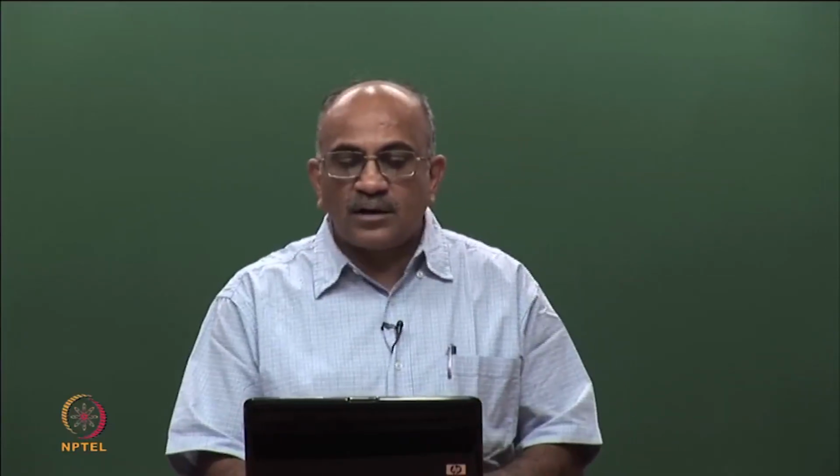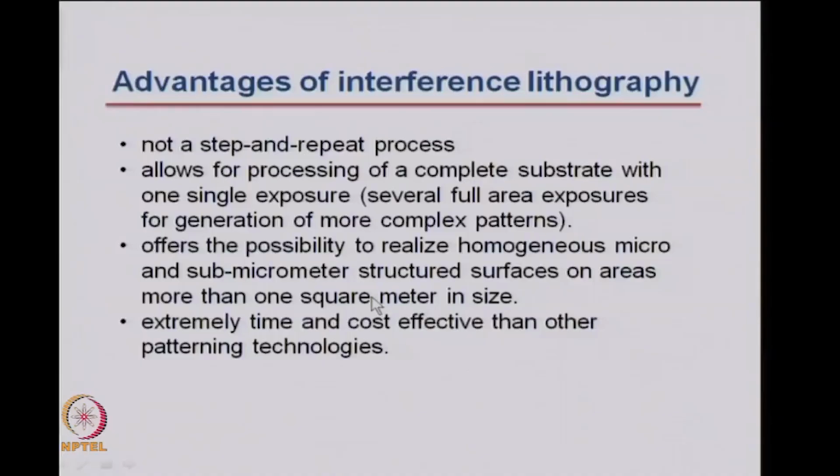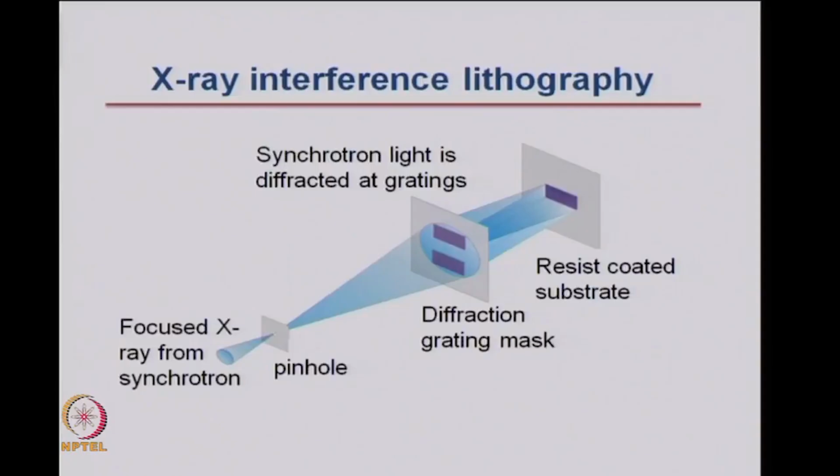It is possible to make very small sub-micrometer structured surfaces on areas which are more than 1 square meter in size. So, it is very effective for large scale structures. It is time and cost effective compared to many other patterning technologies. So, these are the advantages of X-ray interference lithography.